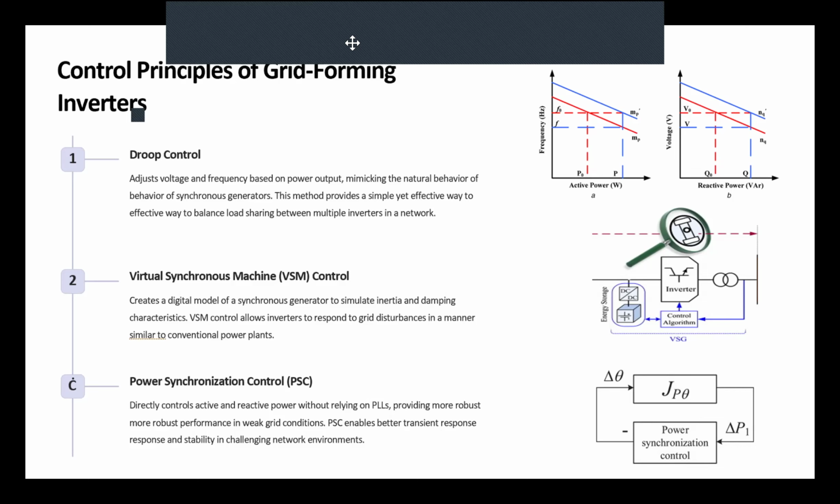We don't need PLL anymore. Exactly. Because now we don't follow the frequency of the grid. We don't follow the terminal's frequency. So synchronization doesn't mean anything. We mandate the frequency at the desired level, which in power systems is 60 Hertz in the United States. So PLL does not have that influence in grid forming that it had in grid following.